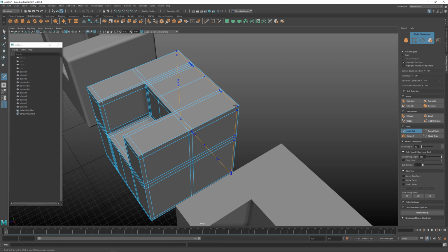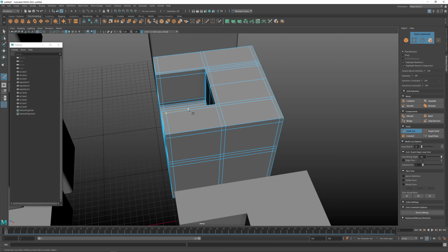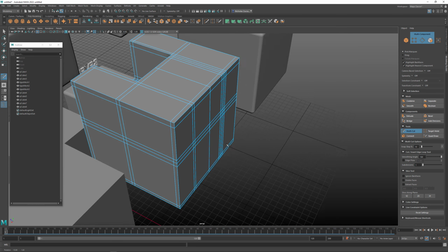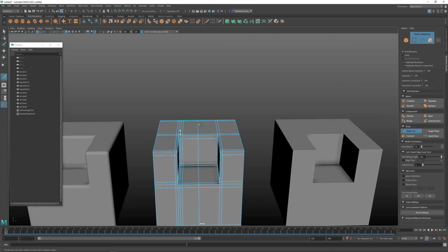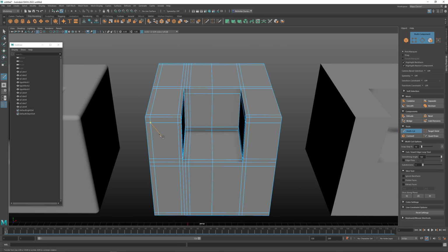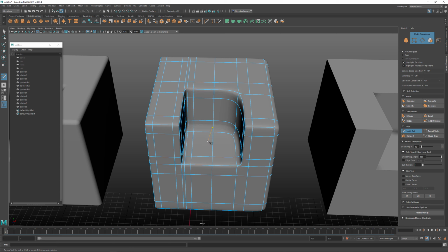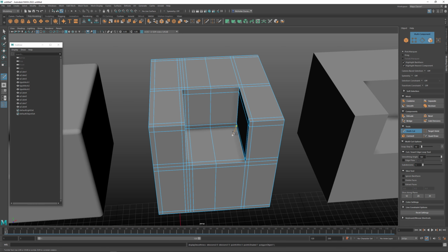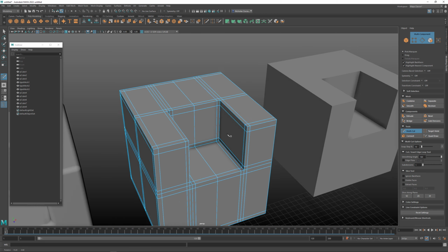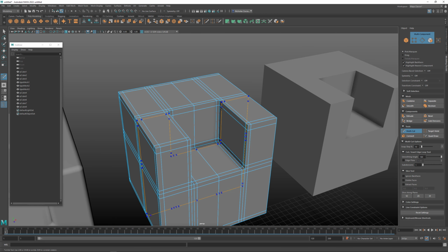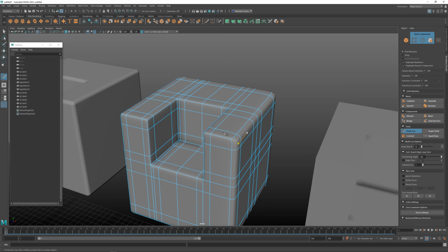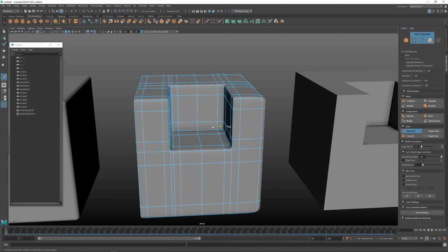And because this is mainly cube shapes, it's not super difficult to do this. So I think we're almost there for having everything we need to hold this. I'll hold down Control and hold this edge here. So I'll tap 3, and I did miss something, so you can see it becomes really obvious when we didn't hit a particular area like this. And now I have to hold this. So let's tap 3. And now we've held all the supporting edges that we need for this.